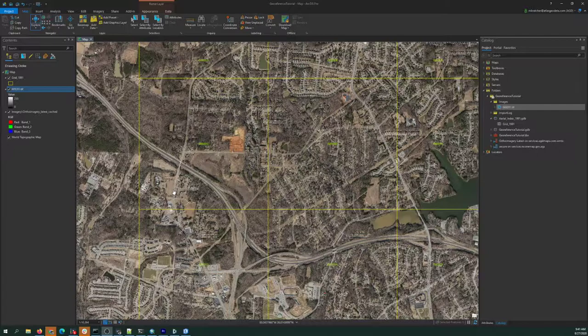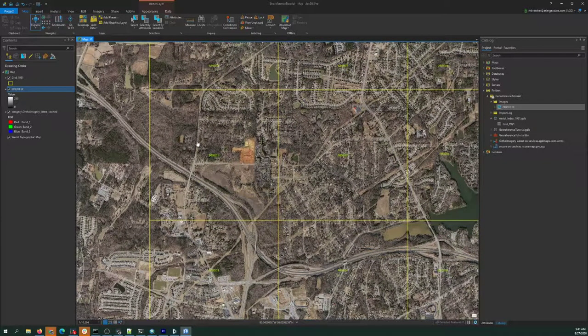So what I'd like to do today is go over some georeferencing in ArcGIS Pro. It works slightly differently than ArcMap if that's what you're used to doing, but the basic concepts are still the same. What we have going on here, we've got a grid to help us locate the general area of our image, which we're lucky to have. You don't always have that luxury. We have an image that we're going to reference and some base imagery to try and match it to. So in this case, we're doing some historical imagery.